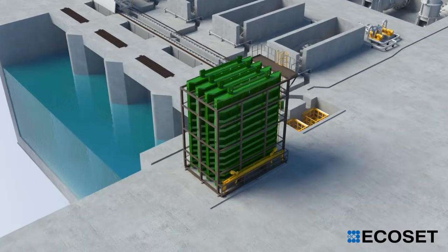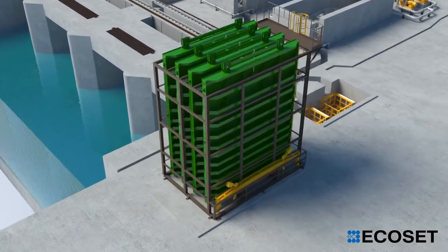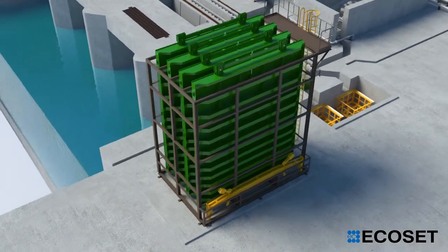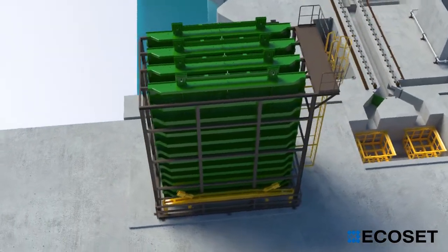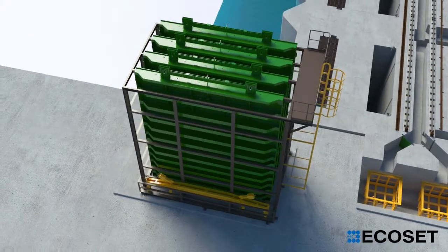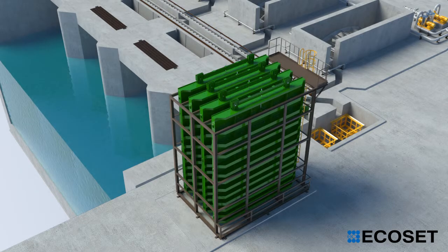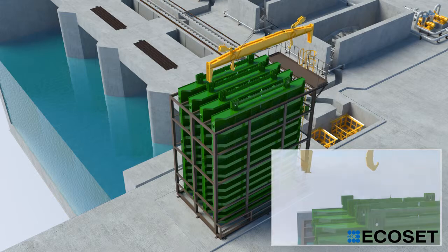The stop gate is used for equipment maintenance. It is used to seal off screen bays and pump bays to allow dewatering of each channel for maintenance purpose. The stop gates have to be stored in a storage stand during the normal operation. In order to lift the stop gate, lifting beam is used.